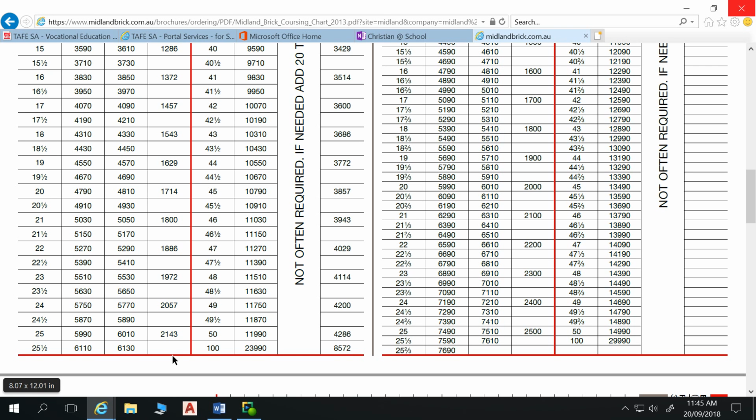Now typically they're 10 millimeters, but the bricklayer might stretch those out to be 12 millimeters or 13 millimeters, getting a couple of millimeters for every brick, enabling them to meet the location of your windows. They're not very happy about that either, but that can be done. The best thing to do is design your buildings with those brickwork dimensions in mind and place your windows accordingly.